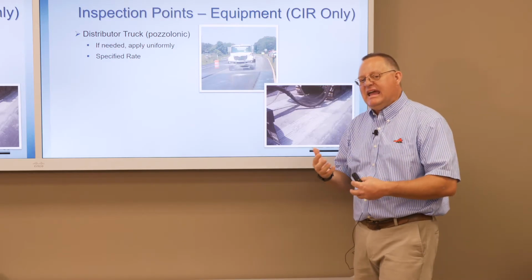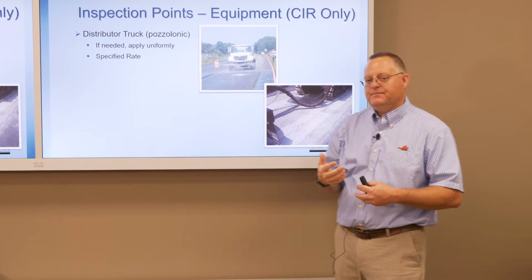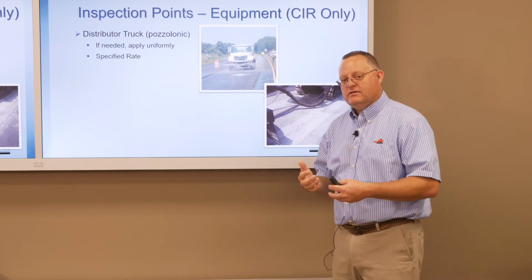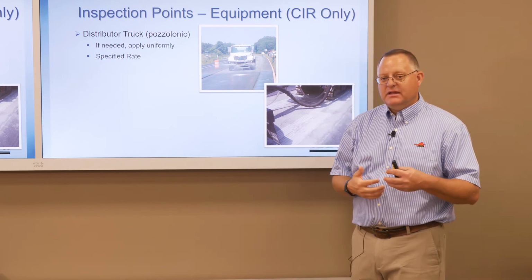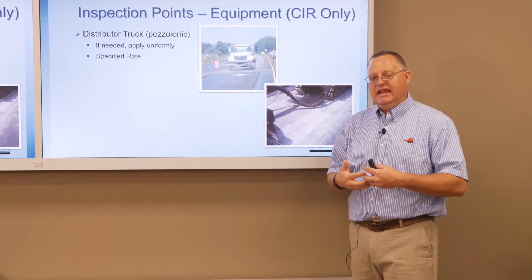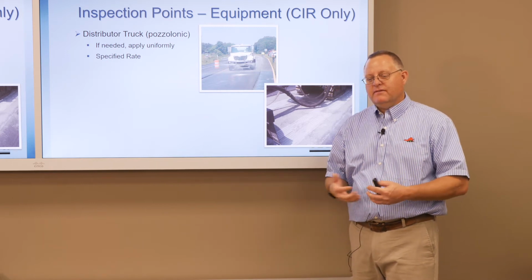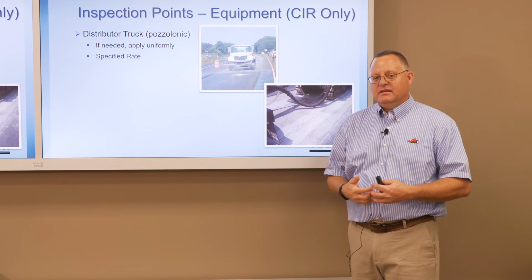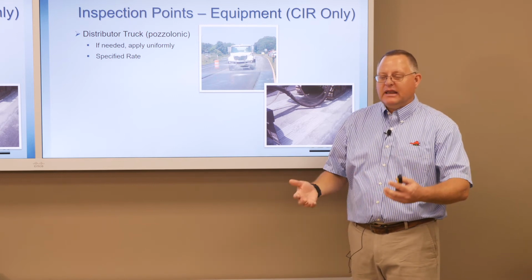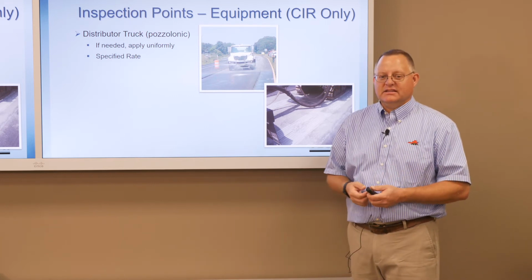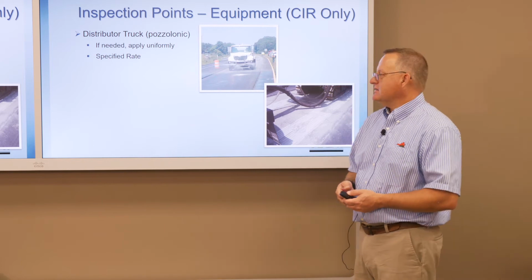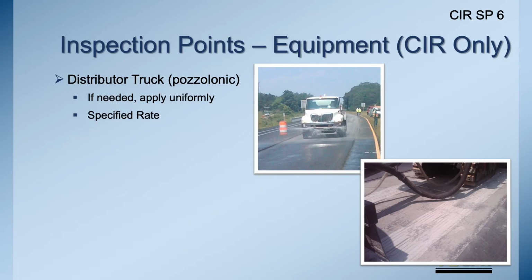Sometimes we need to add that little bit of cement to give us some fines, especially if we're doing like a foaming type process to, again, aid in the distribution of the foamed asphalt, to aid in initial strength gain, but to allow us to actually do the process and get that final product that was specified. And are we at the right application rate? That'll all be determined during the mix design process. So once you get out in the field, you're ensuring that it's being followed.